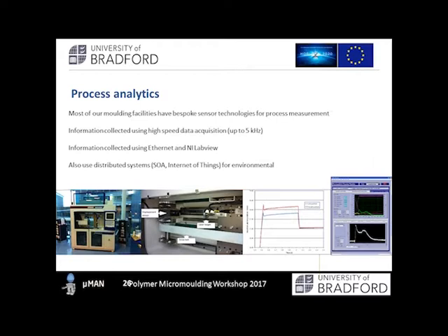We've just got a kind of Hookean spring response of the belt on the machine there, and basically with increased pressures, we see this differential increases because we've got this kind of elastic behavior in the system. But this kind of measurement allows us to implement those changes. We can modify our results so we understand exactly where the flow was at a given point in time.